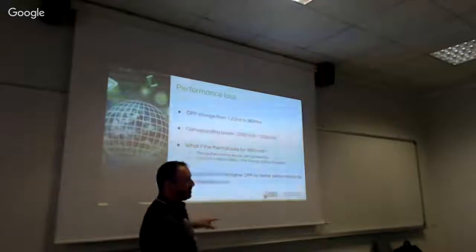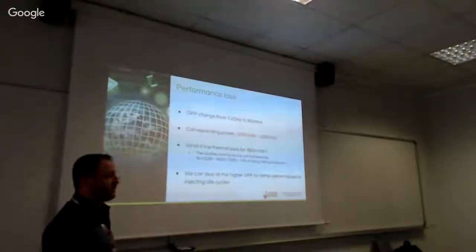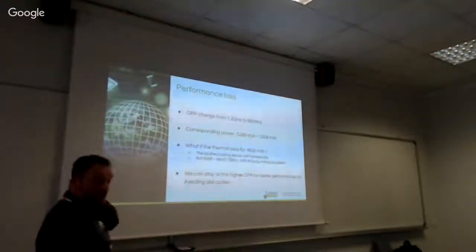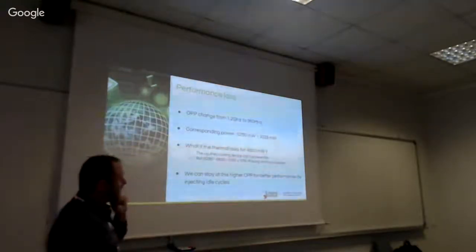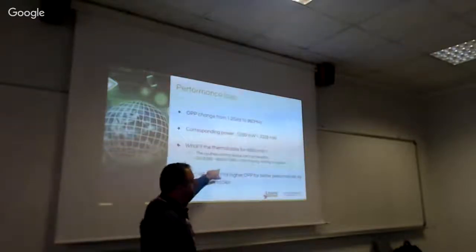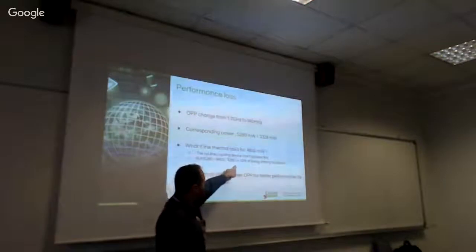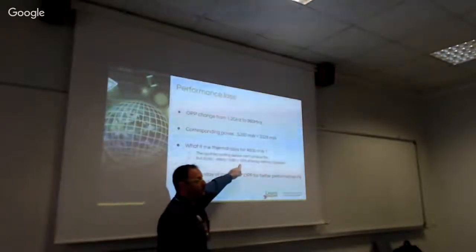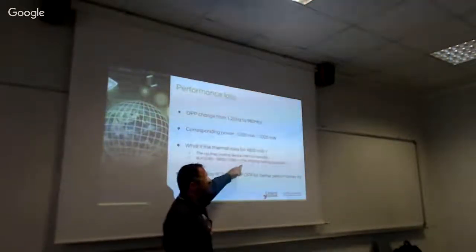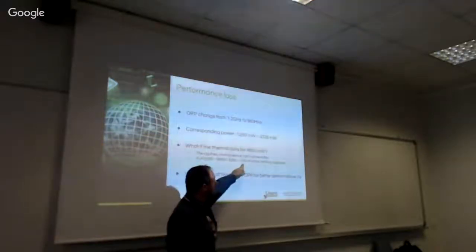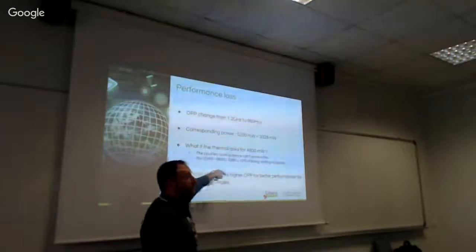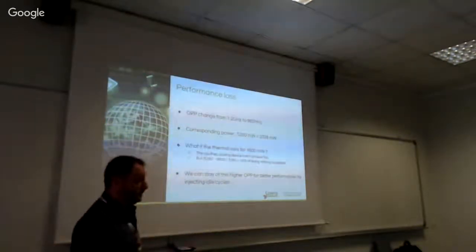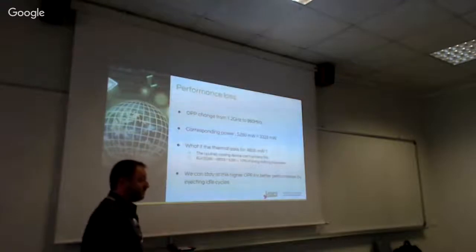Can we do that today? With the cpufreq device, we cannot achieve that. But if we add idle injection at this point, before changing the OPP, we can be injecting idle cycles. We have the same power, and because we are at a higher OPP, we are faster.